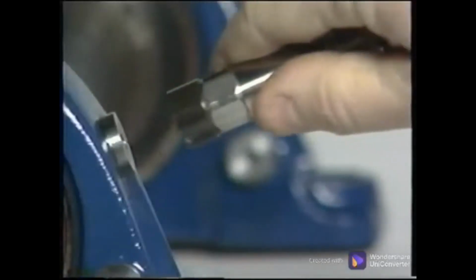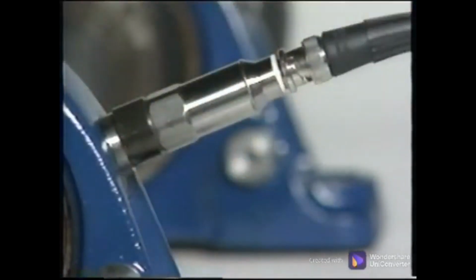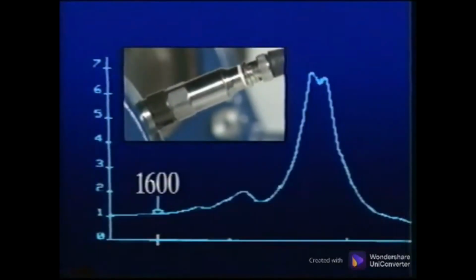This small magnet has a flat surface for mounting. To avoid erroneous data due to unstable mounting, it should be used only on flat surfaces. The linear range of the same sensor with this magnet mount increases to 1,600 Hz and makes it even more desirable if the mounting surfaces are flat.